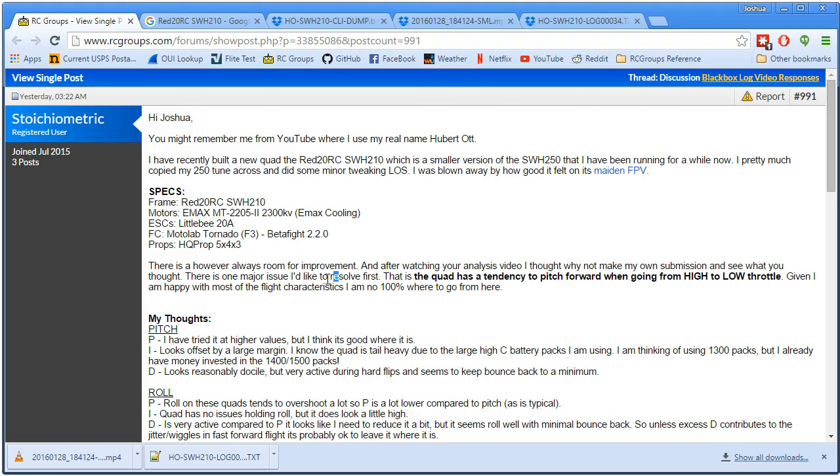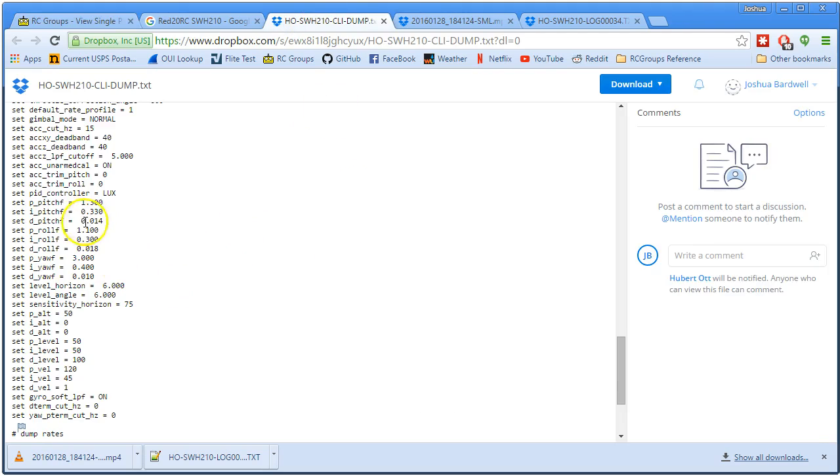And so you've got an I gain of 330, and my experience with my copters is that I gain on pitch usually ends up in the realm of 50 to 60 in order to control effects just like this. Not so much when I punch the throttle, but when I climb out and chop the throttle, or if I'm in a sharp turn and I chop the throttle, the copter needs to maintain stability, and that's why I end up raising I on pitch. So potentially you'll need to raise I on pitch, but don't do that until we check and see if your P is raised high enough.